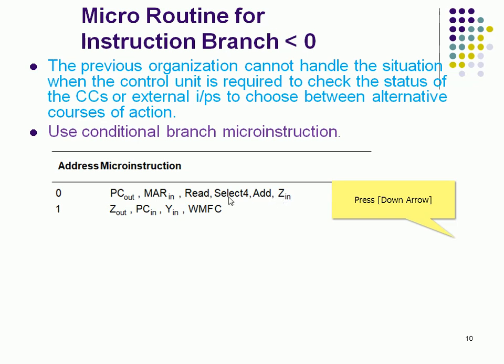That's why we get a green signal from the memory. After that we get the data at MDR out, and that instruction is kept in the IR of the CPU. The IR is responsible for holding the instructions or data coming from the memory to execute further. So this complete first 0, 1, 2 steps are related to the fetching phase.